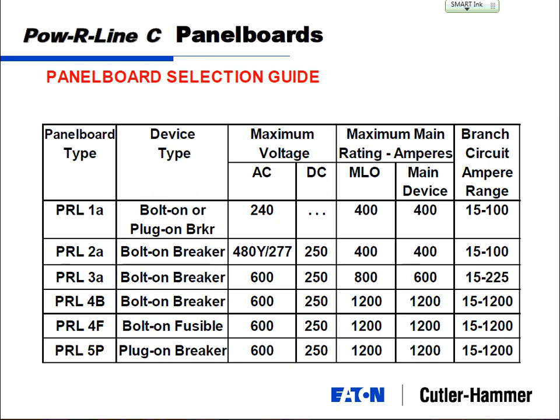As we talk about the circuit breaker, maybe this is a good time to show you that circuit breakers can trip by one of two means. You're really talking about the trip unit, or the tripping function, of the circuit breaker. One is called the thermomagnetic trip unit, and the other is a solid state trip unit. The thermomagnetic trip unit is just like it says: you've got a thermal and a magnetic protective feature.